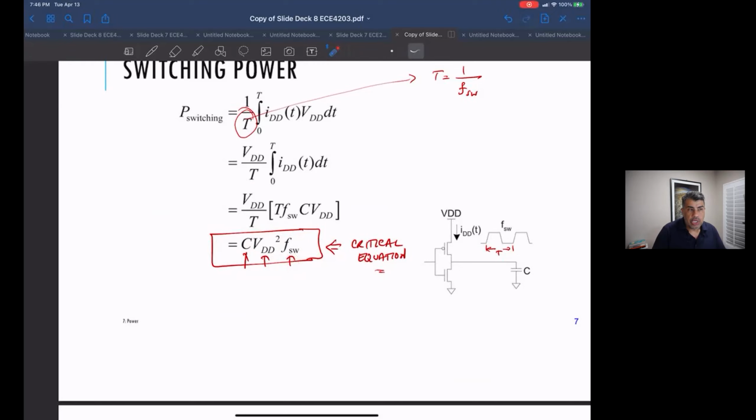But you have to remember that the majority of the circuits are just sitting there quiet. They're not switching. Remember that the only time we're taking power in this cycle is when the PMOS is driving this load from 0 to 1. If the circuit is just sitting here, there's no transient power consumption, okay?